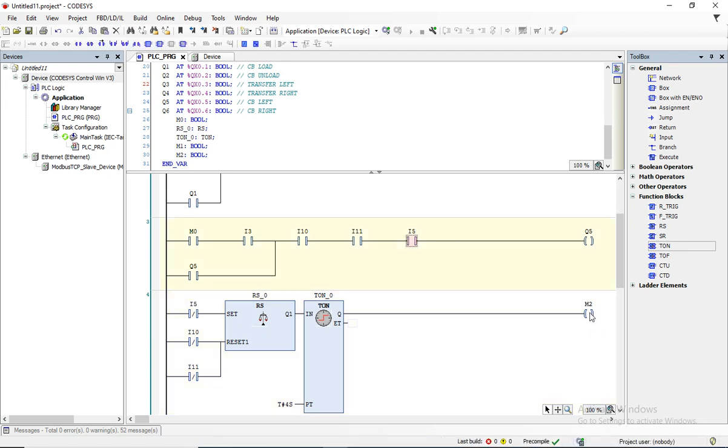We do have a normally closed, so for demonstration purposes let me just change this one to a normally closed. Set. Okay, so this one becomes M2. Enter. And this one we leave as it is, becomes M2 also. Enter. Right, and then just download the program.